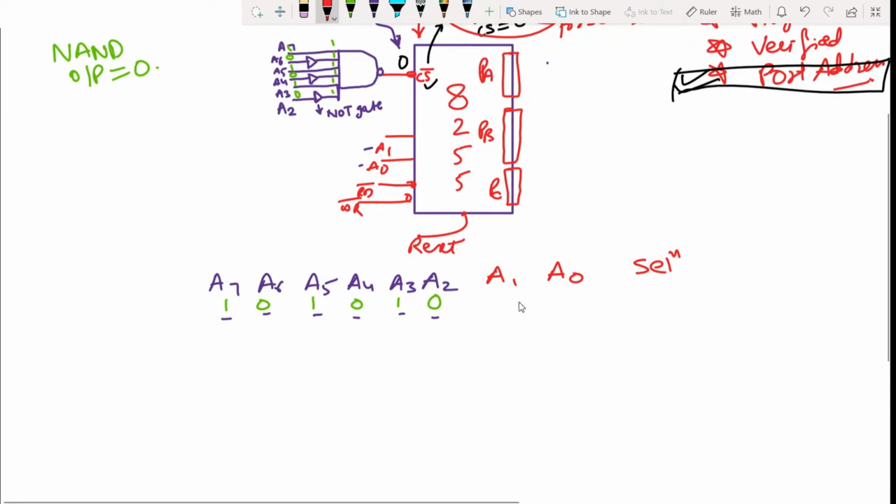Okay, then that's better if you are able to understand. So this is what I received from the circuit of NAND gate. What I did in the NAND gate is this signal represents the CS bar, because what is entering inside the CS bar is totally dependent on these 6 inputs. If any one of them changes its state, the value of CS bar will be changing. So actually what we have done is we have created a circuit on which CS bar will be dependent.